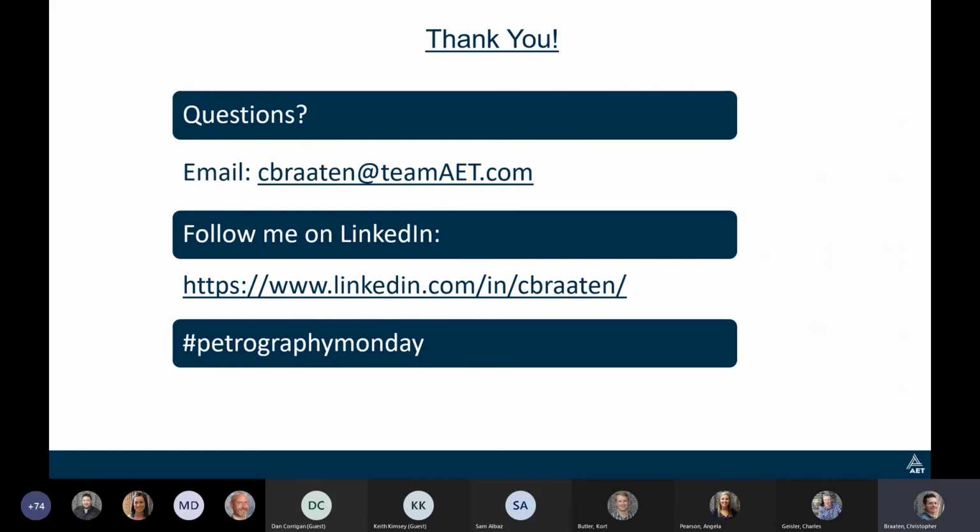Is efflorescence and ASR similar? No. Efflorescence is typically crystalline precipitate growth on concrete surfaces or inside concrete. And ASR is that specific reactivity, and it creates an amorphous gel. So I would say that they are somewhat similar because they're a chemical reaction creating a precipitate, but different in the nature and type of precipitate created. And then